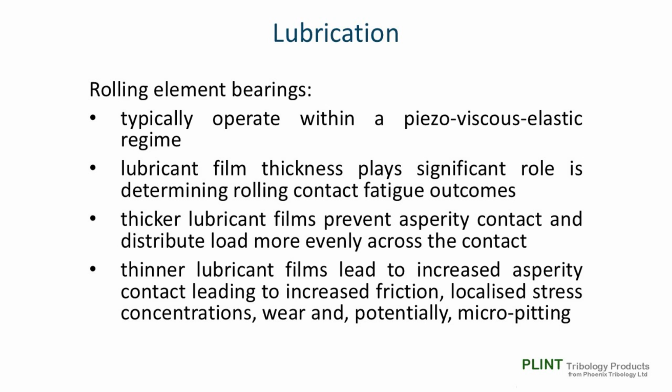In a rolling element bearing, pressures within the Hertzian contact are sufficient to cause elastic deformation of the rolling elements. The lubricant, providing it has been properly entrained and carried into the contact, is subjected to these high pressures, and this causes a massive increase in its effective viscosity.